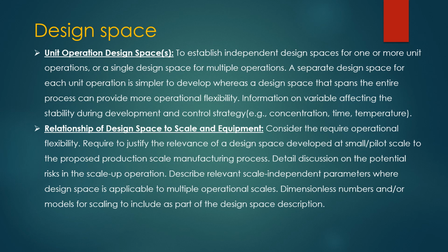A detailed discussion on the potential risk in the scale-up operation is required to be included. Describe relevant scale-independent parameters where the design space is applicable to multiple operational scales. Dimensionless numbers and/or models for scaling should be included as part of the design space description.